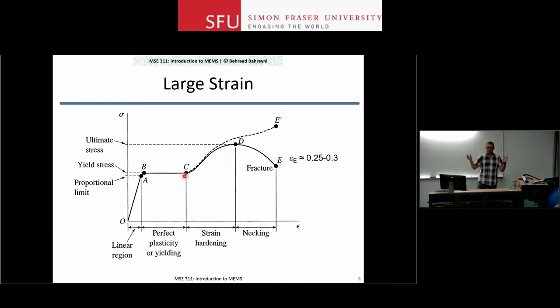Once you remove the stress, you will have some permanent deformation of the material. If you keep increasing the strain or stress, you will go into a hardening phase, and then eventually the material fails. Now, this is for your typical material, right? Very general situation. And just notice that strain axis is not drawn to scale. You usually don't really get that much of, let's say, range of changes after you go past the yield stress. Things usually happen very quickly beyond that point.